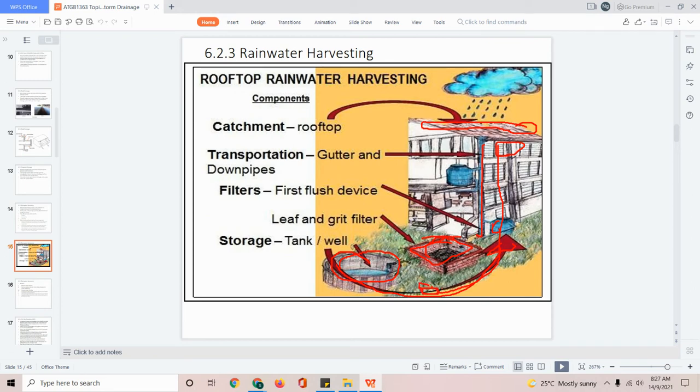In addition to that, we also need to install an additional pump. So it will cost a bit of electricity and upfront cost to purchase the pump and all the piping. Once you have that, you can have two tanks, one from the main water supply and another one from our rain harvesting system.